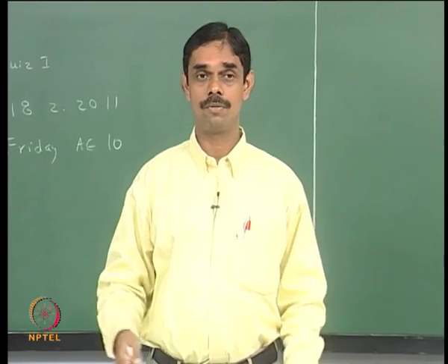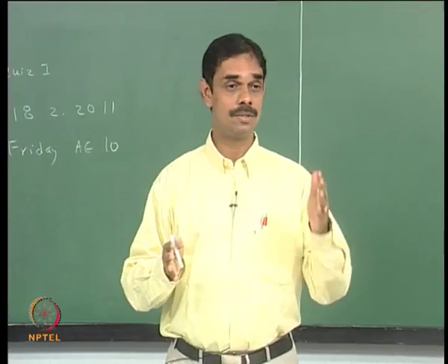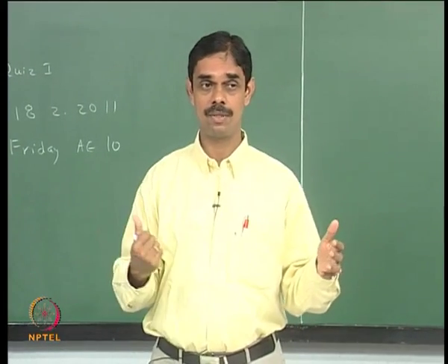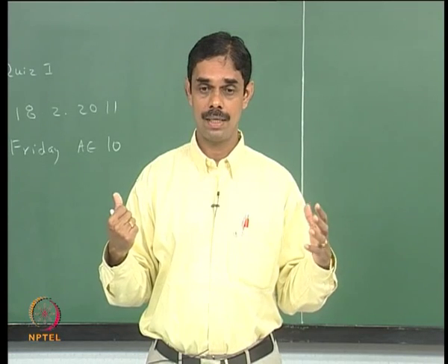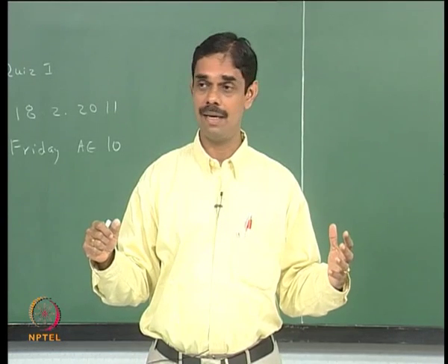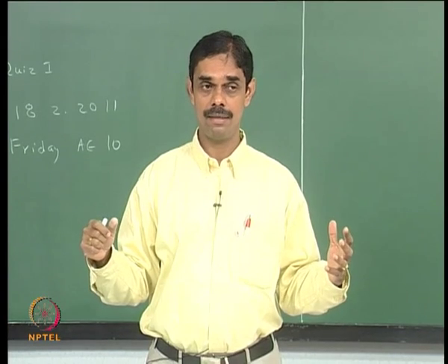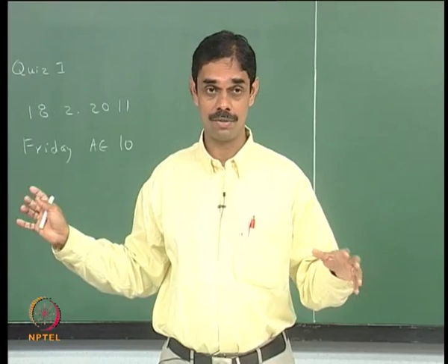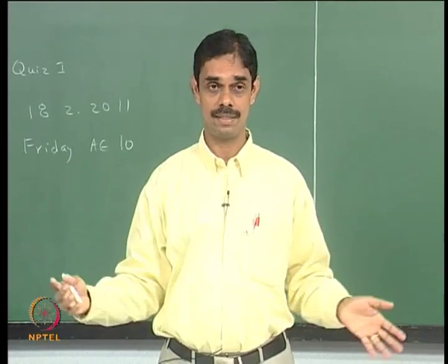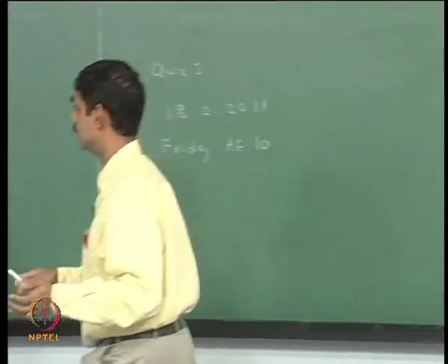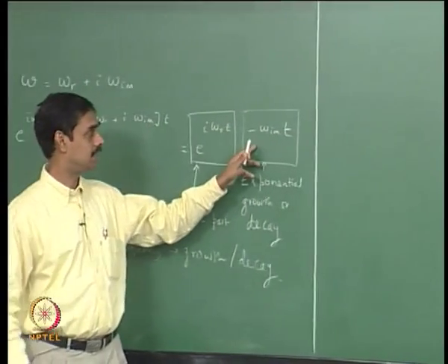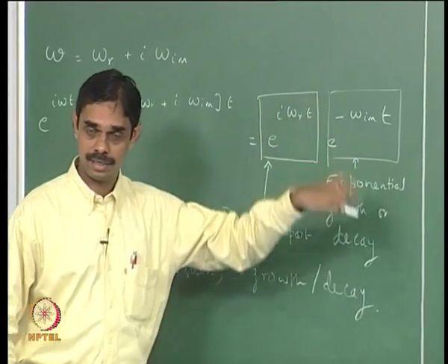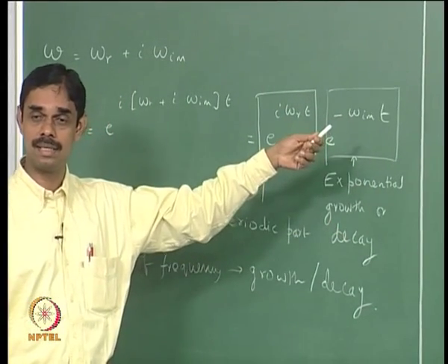For example, suppose you found the impedance of a propellant or something by putting a loudspeaker, exciting it, and checking what the amplitude of the wave is. That is not an end by itself for us. In the end we want to solve the eigenvalue problem without any loudspeaker and see if the system will get self-excited. A self-excited system would mean a growing term, e power alpha t, and if it is a stable system it will be an exponentially decaying term. That is what we are interested in eventually finding out.